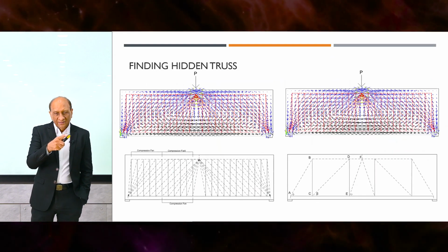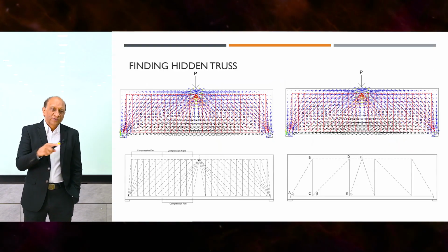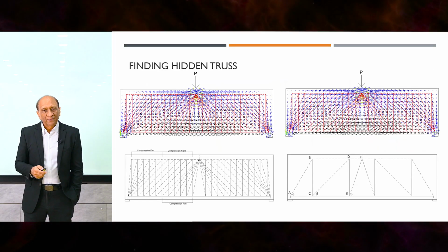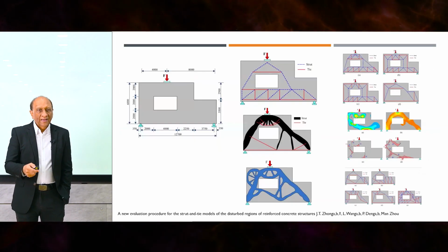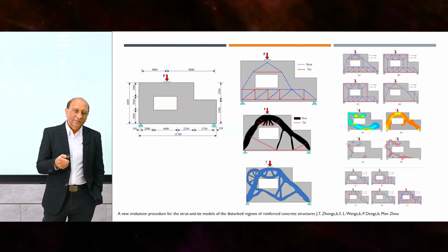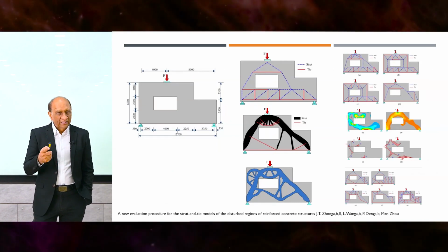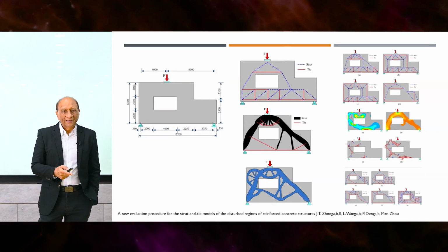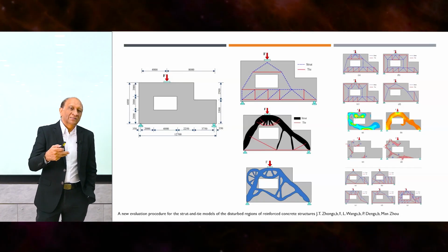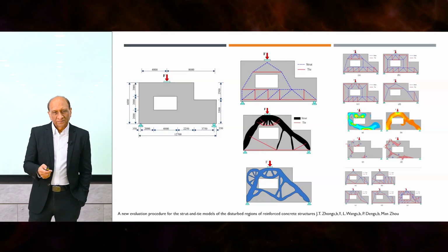And this is, once again, the same thing. You can go further if you mesh it very fine, and you can find these struts and ties more reliably from that. You can go on to solve more complex structures like this one here. And if you do this nonlinear, then you can do a lot more. There is software out there which is now doing it that way. So the strut and tie model concept is coming back with nonlinearity in it now.